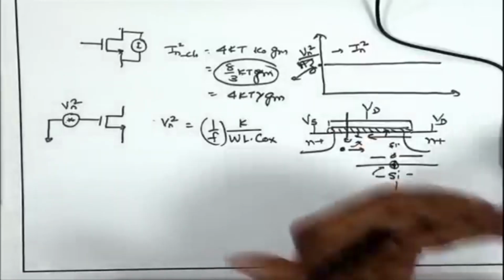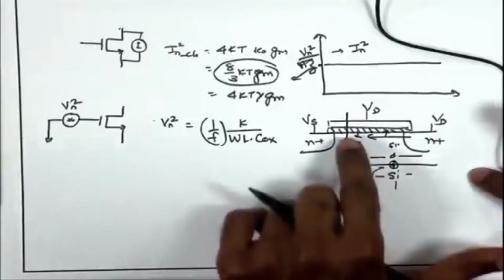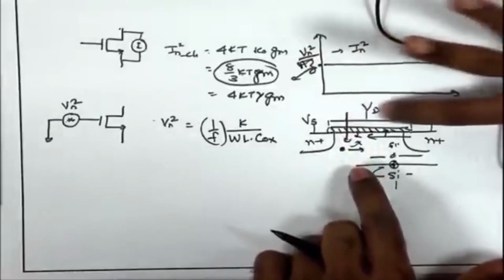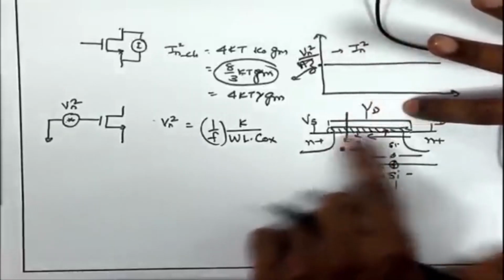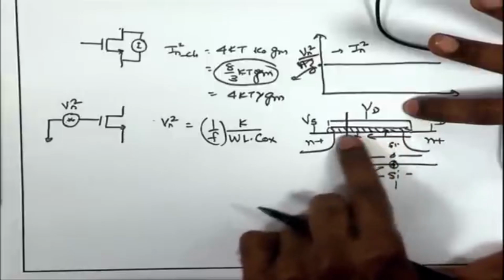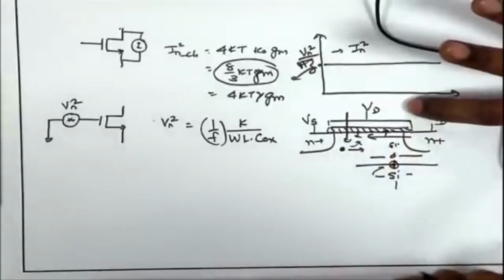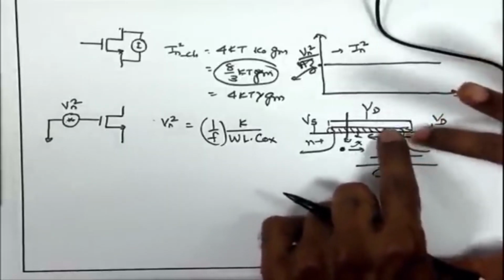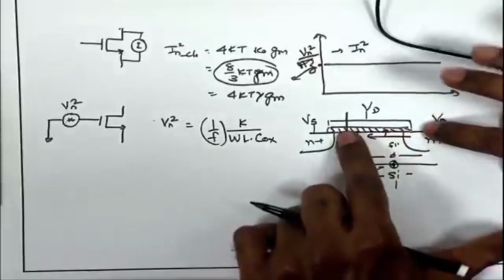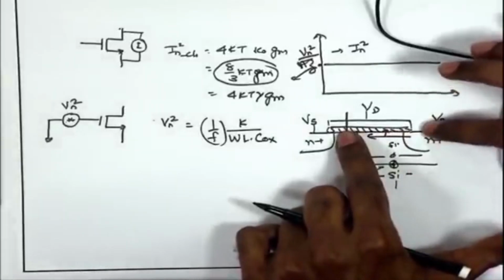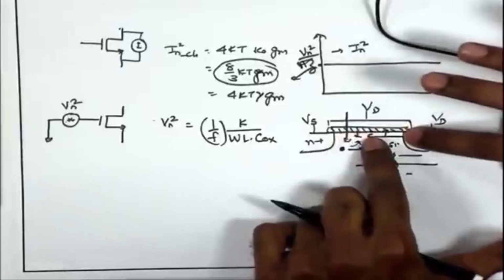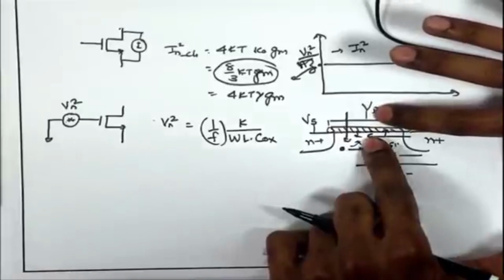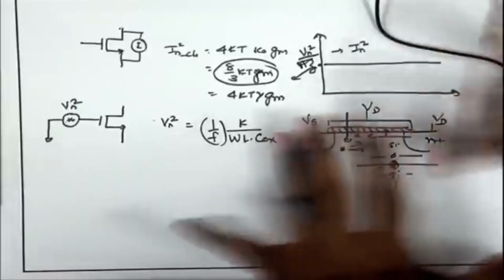So, remember how did we define threshold voltage? Threshold voltage concept came because of the accumulation of charge. So, we need a certain minimum positive charge deposited on the metal gate to get a sufficient number of negative charges inside the channel, so that the continuous channel is formed. So, suppose at a certain instance I already pump in some negative charges, they get trapped into the oxide over here, then you already have some trapped negative charges and you may require smaller positive charges to balance that total negative charge. Therefore, threshold voltage can reduce.